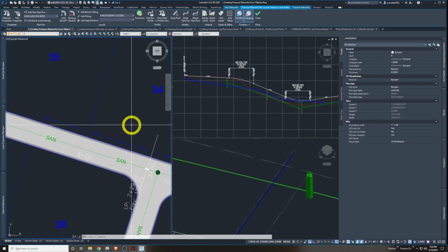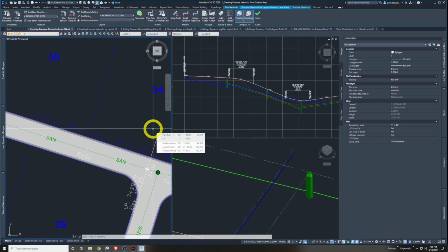To also help guide your design, there's a further item called a compass. So that displays the bend angles and deflections that are available to you as you design out your pressure pipe network. So remember I was talking about bend angles and deflections of pipe is a little more common to pressure pipes as certain materials and lengths have different deflection angle allowances, and being the pressure pipes, they have different precise fittings connecting them. So we're going to see what that compass means here in a minute.